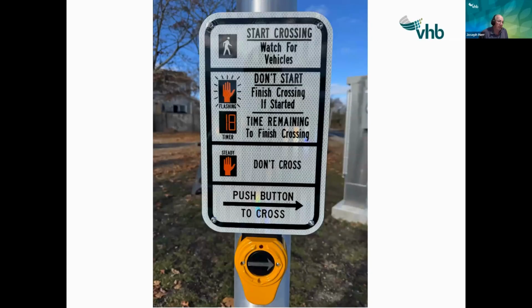This is what it typically looks like. Again, there are various vendors that are out there. Accessible pedestrian signal buttons typically look like this. This is one of the signs that is shown in the MUTCD. It's very informative to let the pedestrian know what the different displays are. The arrow indicating what direction is on aligns with the arrow that's on the button to show the direction of the crossing with the confirmation light.